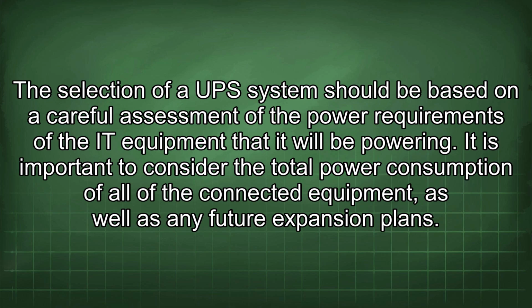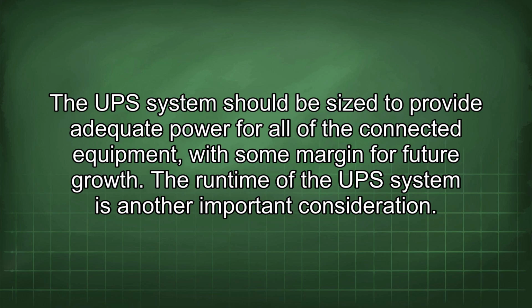The selection of a UPS system should be based on a careful assessment of the power requirements of the IT equipment that it will be powering. It is important to consider the total power consumption of all of the connected equipment, as well as any future expansion plans. The UPS system should be sized to provide adequate power for all of the connected equipment, with some margin for future growth. The runtime of the UPS system is another important consideration.